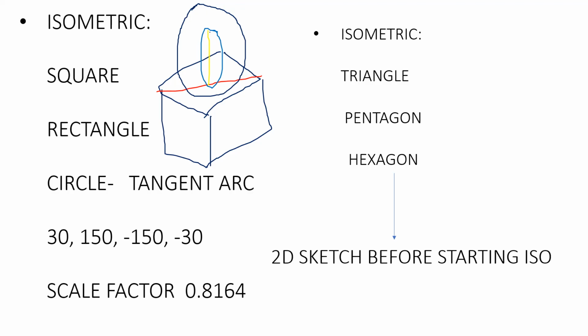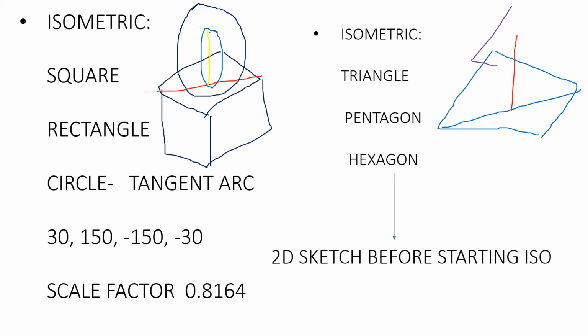If you take a hemisphere, so if I have the top face something like this square, locate the center, then draw the radius, then draw the top face of the hemisphere, again a circle here, something like this, then convert this to the scale. Now come back and draw the arc like this. That is the hemisphere. Those two are very important.